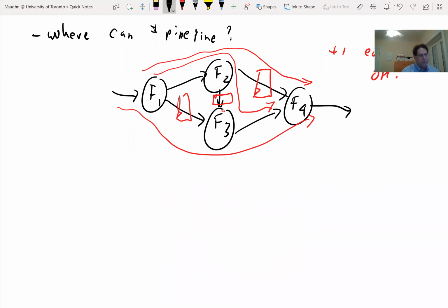So the fundamental rule of pipelining is balance all the latencies from input to output. This, what I've drawn here, is what's called a feed-forward circuit. So the data flows from inputs to outputs, and you can actually define a data flow direction. So that's actually a nice style of circuit. It's because it's easy to pipeline and therefore easy to get high performance on. For those feed-forward circuits, if you can define a cut between the inputs and outputs, and you put a pipeline register at every one of the edges that you cut, it's legal.